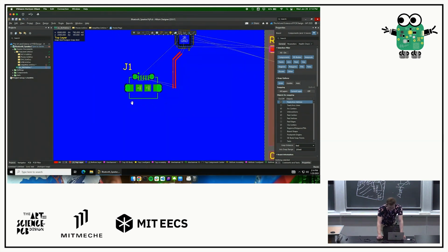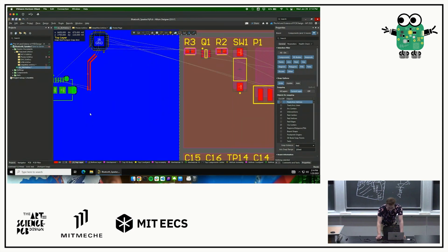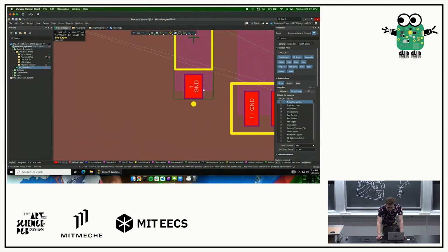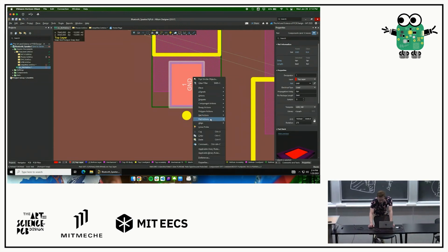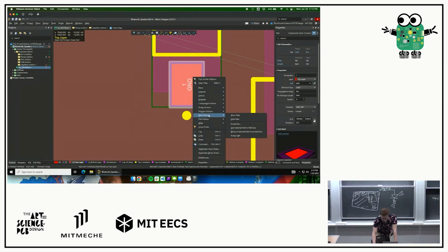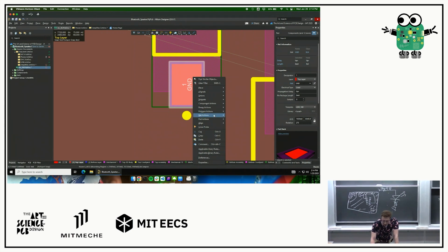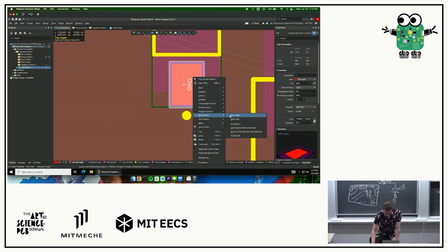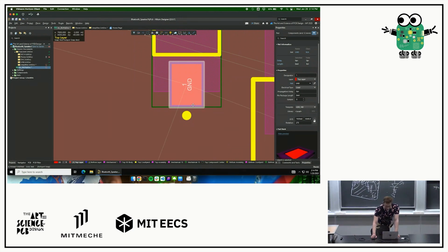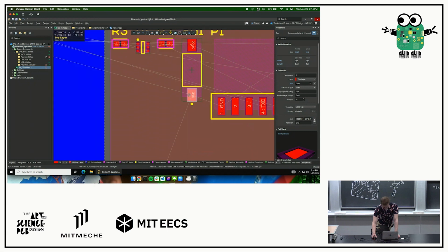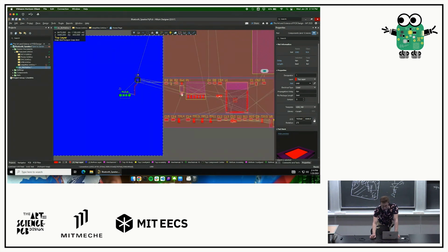But if you're just doing generic signals, what you can do is go in here, and if you go to net actions after right-clicking something, you can hit show or hide nets, and that'll choose whether or not the power and ground shows up in your rat's nest. So right now I think it's disabled. I could hit show nets, and oh, now we have this big meandering bit that goes everywhere throughout the board.